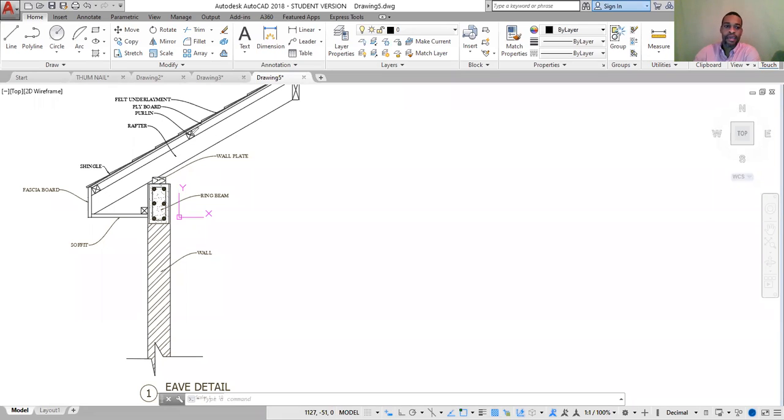not every roof framework has a purlin, and purlins are only applicable or used when we have a roof like a metal or zinc type of roof. That's when we use purlins. The purlin is basically where we would nail the roof down onto the rafters.